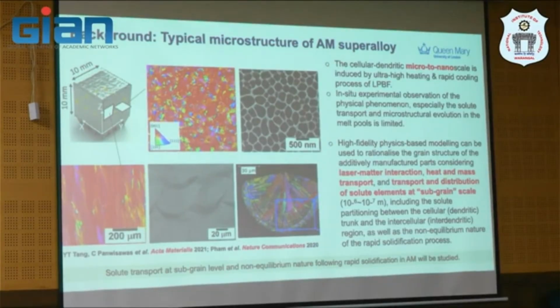And this is the typical characteristic microstructure for AM, LPBF especially. Along the build direction and in the transverse direction, you get different microstructure clearly. And this structure, when you zoom in, is actually a cellular structure. If you zoom out a little bit, you will see some zone like this. That's what I call the solute trapping zone. And this is quite important. You will see this contribute to different microstructure locally, so you have equiaxed and columnar mixed together.